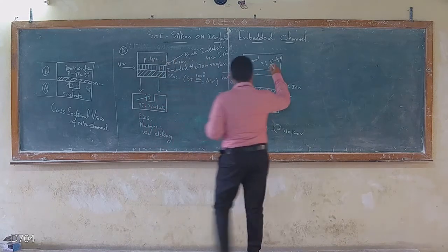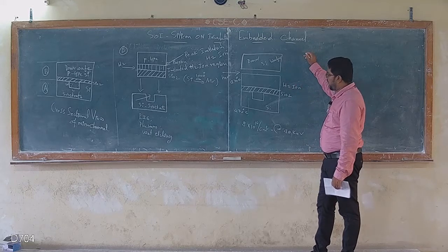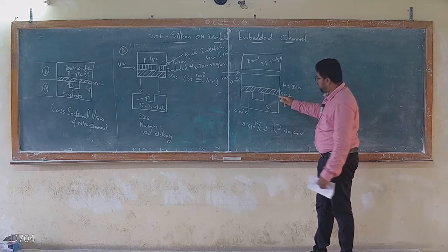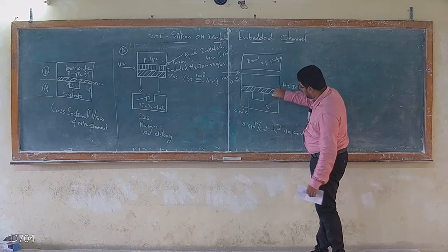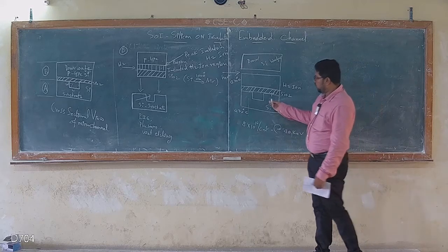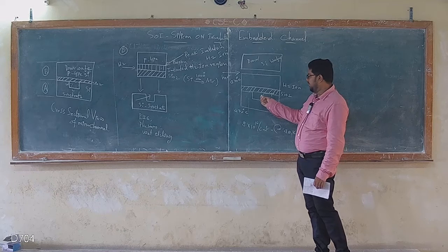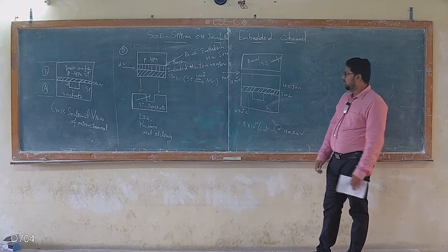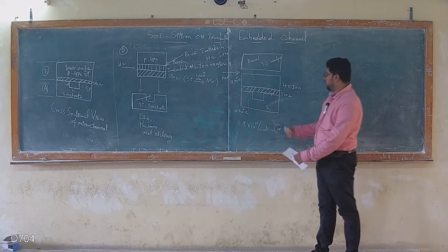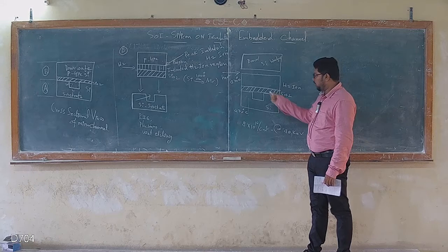Now the donor wafer is removed from the cross-sectional view. The donor wafer is moved away, and the lower embedded portion of silicon with silicon dioxide is obtained. Now you can understand the microfluidic channel got sealed or encapsulated by the silicon dioxide. This is the easiest method using the SiO2 layer. Why do I call it an SiO2 layer? Silicon on insulator, with the channel.